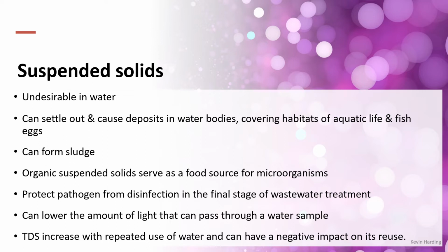Suspended solids are going to be one of the important aspects of the solids in this one, as they are undesirable in water. Because they are suspended, they could settle out, and when they settle out, they could cause deposits. So you get a sludge at the bottom of dams and lakes. That settling can also cover habitats of either the fish or any other wildlife, particularly of the eggs. As I already said, it can form a sludge.